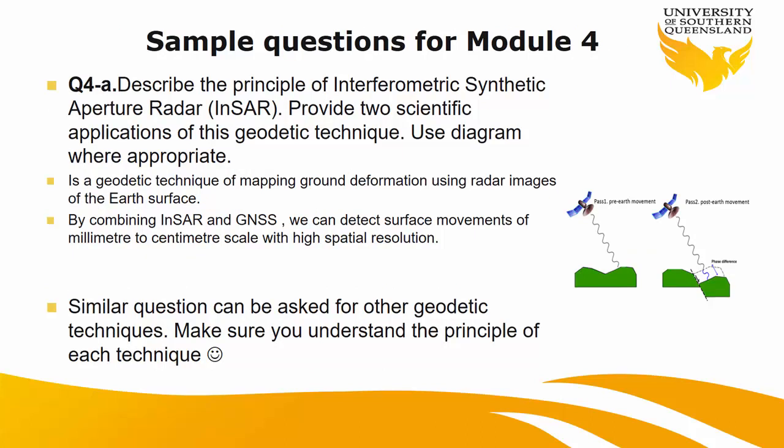It can be InSAR. We again know how it works. Anyone remember InSAR? It was very easy. It measures land movement using the phase shift, getting measurements over time, like every 10 days or so. Then it can measure movement, whether it's uplift or sinking. Land movement can be measured using the phase difference. And we did the exercise with the software that showed us all those phase shifts in the area due to the earthquake, pre and post earthquake.